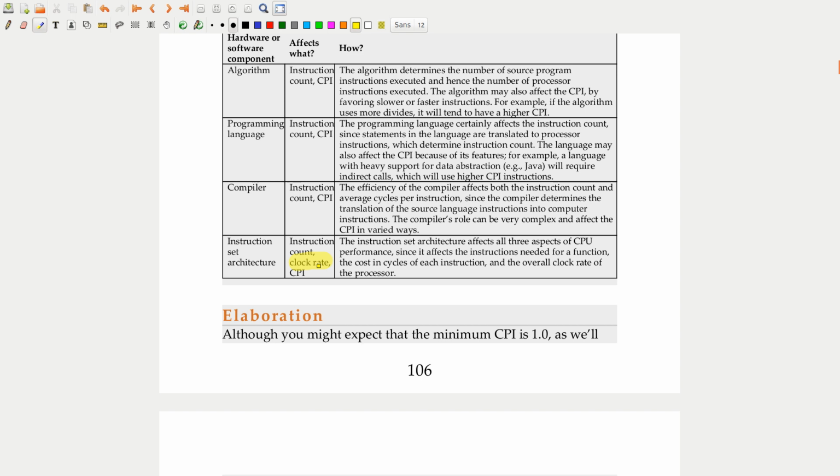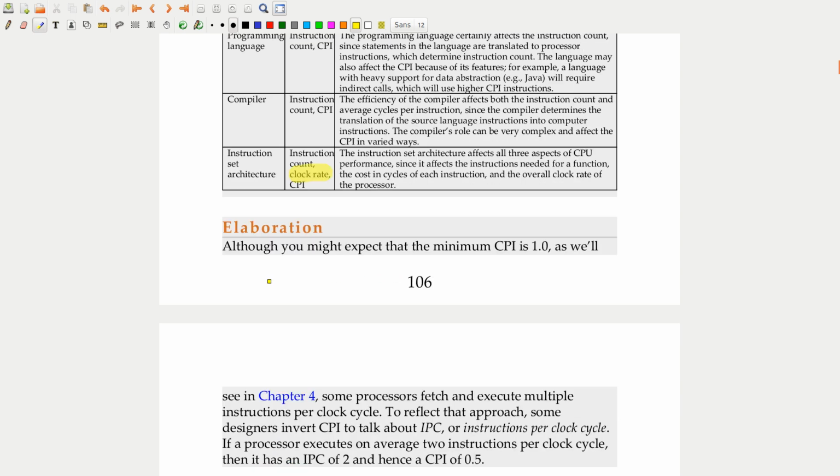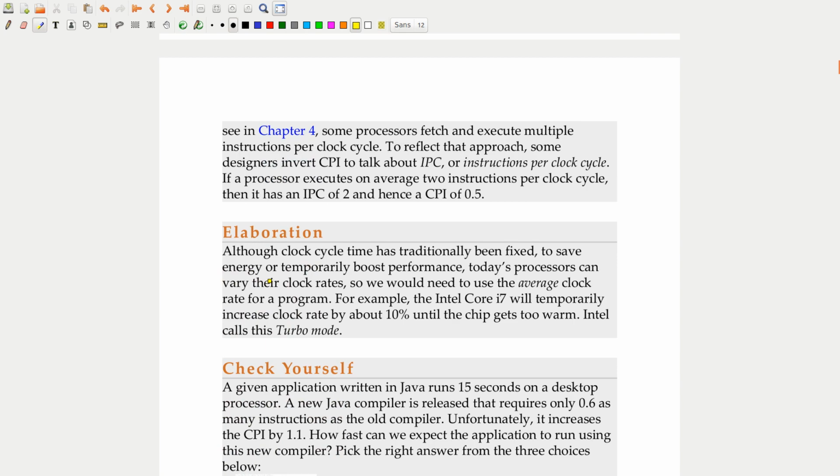If we make design decisions at a hardware level, they influence how fast we can run this clock. We can't run a clock faster than we're able to complete some basic part of the pipeline, because then we're going to lose data someplace in the middle.